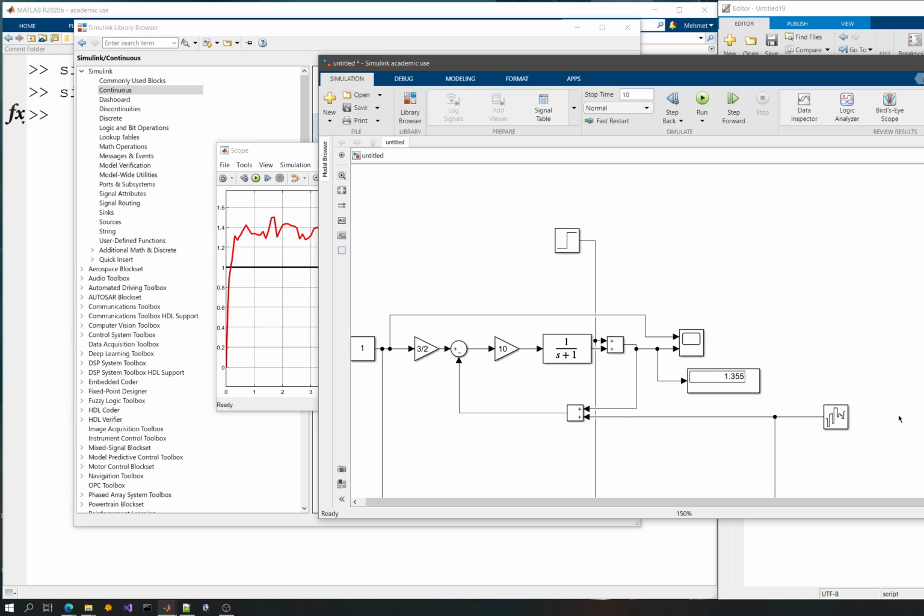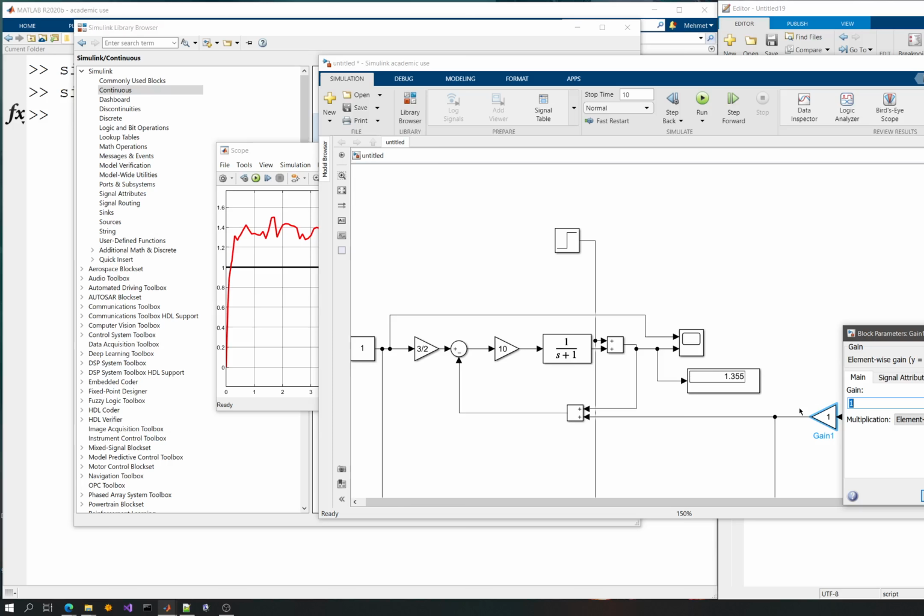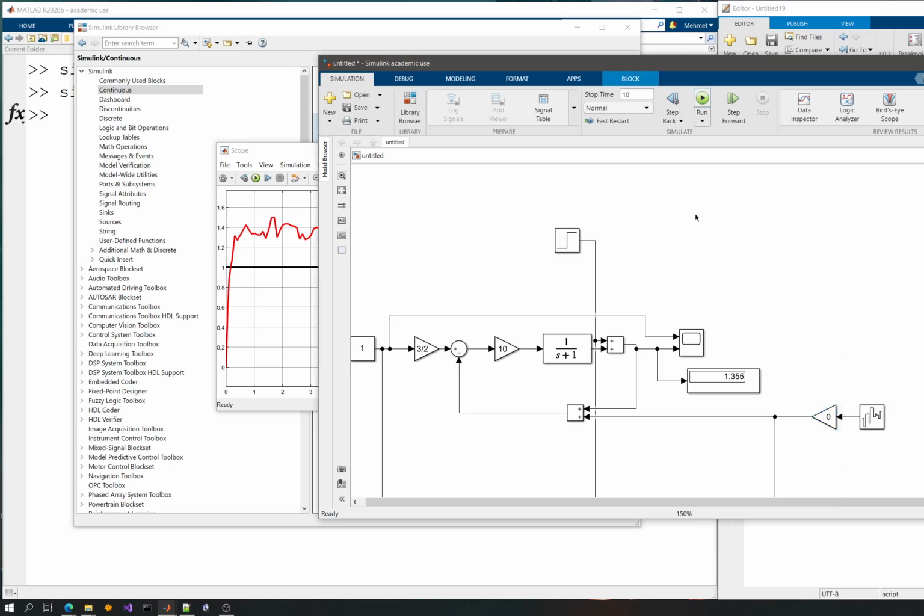Now, if I do not have this, maybe we should use a zero gain for that. There are also some other structures or components that can be useful to switch off stuff here, but using a zero gain is the best and quickest way for disabling noise. And I might also use this here and paste it, Control I, and then go ahead and use this as a gain for my step function here. Now they will together build my system here.